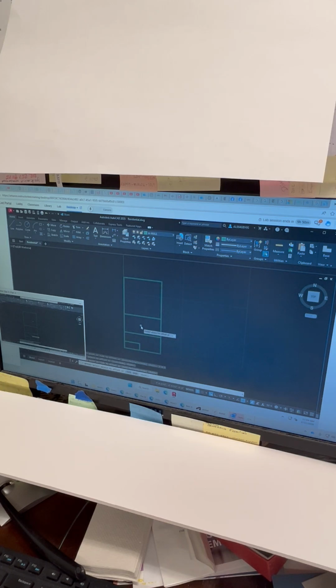All right, while I'm still in the command, I might as well go ahead and locate this wall here at 8'3". Or if you've already exited the command, just start it back up again. Put 3.5 inches as your default dimension. And we're going to select this inside face line on the west wall, the inside line. And we're going to move our mouse anywhere to the right, and we're going to type in the distance, 8'3".